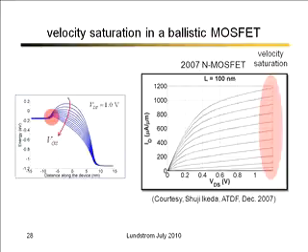You go in the lab, you measure a transistor, you see that kind of IV characteristic, you say, I'm dealing with a velocity-saturated MOSFET. Now, that was very difficult for us to understand because the more we understood about transport, the more we realized that the velocity does not saturate in high electric fields in short devices. It just gets higher and higher.